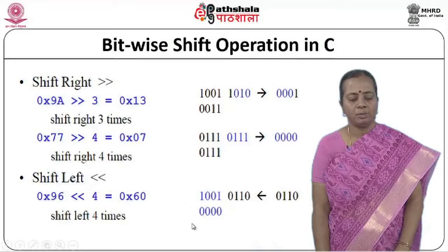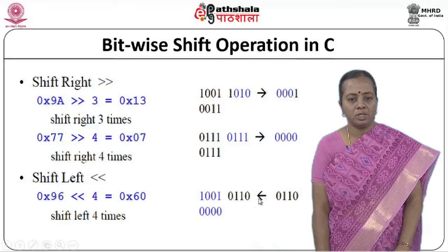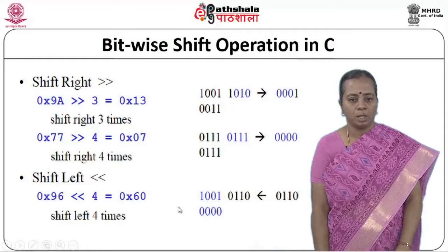So, when I am shifting it left, you just see that this 0 1 1 0 comes to this position and 0 0 comes to this particular position. Just see that this is nothing but 6 and this 0 is coming over there, all 4 zeros have to come over here. So, you just see that the whole thing is getting shifted by 4 positions, so that this goes completely and this particular nibble comes over here and the right side nibble will be 0 0 0.